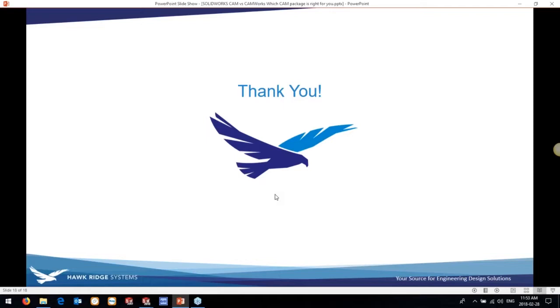From the same company that produces CAMWorks, there's a tool called NestingWorks, which will allow you to take a part or an assembly and say, hey, I need 20 of these. Go and nest them onto a sheet. You tell it the sheet and the orientations that are allowed for that particular part, and it will spit out a SOLIDWORKS assembly that you can then program in either SOLIDWORKS CAM Professional or CAMWorks. So I hope that answers your question. If not, just let me know and I can go into more detail with it.